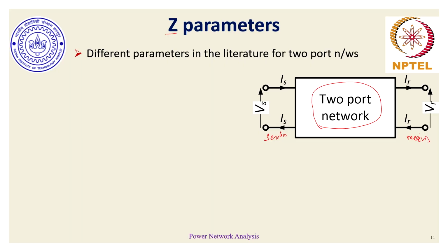If you're talking about Z parameters, which are impedances, then for an equation, on the left hand side there should be a voltage expression equal to a current expression multiplied by the corresponding impedance. That's how impedance or ohms are defined. So in the context of Z parameters, let's say we call them Z11, Z12, Z21, Z22.